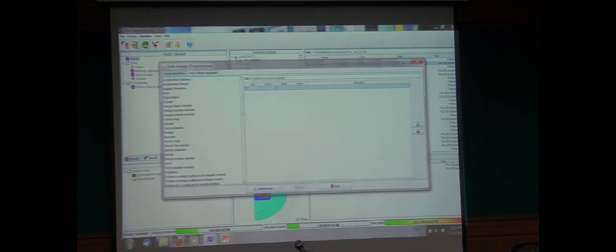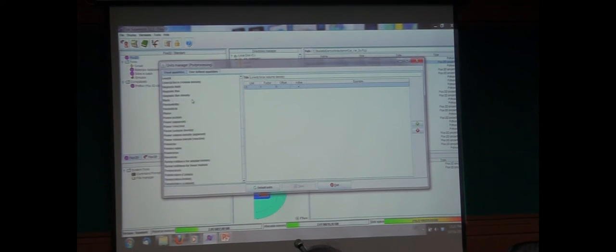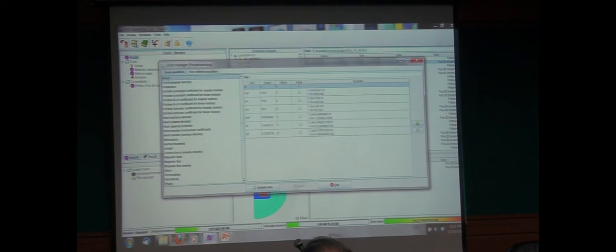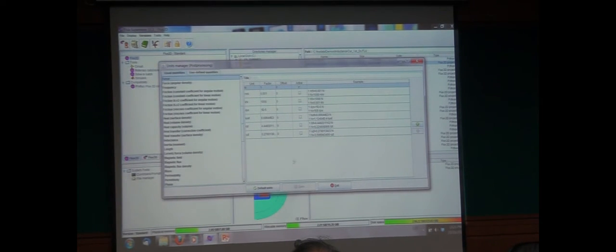First, the units. Right there, these are the units that are available. I mean, this is the environment where you set the units. So, for example, if I take a unit like force, you can see I have newtons, I have dyn, ton force, pound force, and ounce force. So I can select, by default it works in MKS, and you can actually choose whatever you want. Once you've set your default unit, it means that when you work, it will automatically use those units.